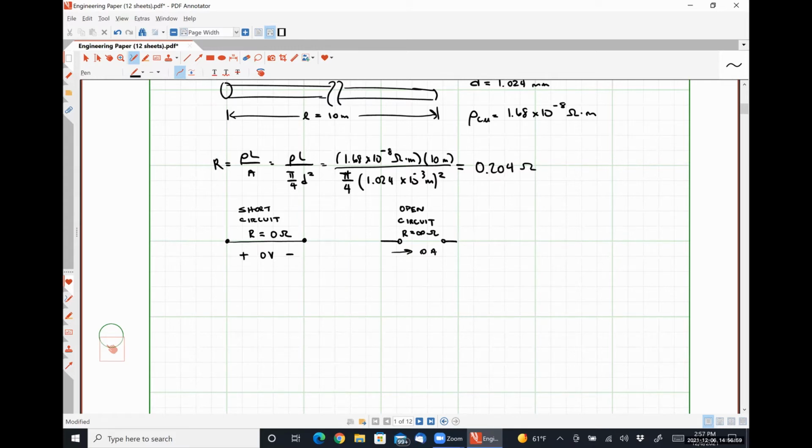And the reason for that is the wire actually has some sort of finite resistance. Okay, it's going to be very, very small, but when you have a large voltage drop, and large in this case is, you know, a volt or two over a very, very small resistance, that means that the current flowing through it is just going to be the maximum of whatever that source can provide. So for a AA battery, that's going to be a couple of amps. Not enough to do anything super harmful, though it could cause the battery to maybe explode. They can definitely get hot enough to melt a battery pack and all that kind of stuff.